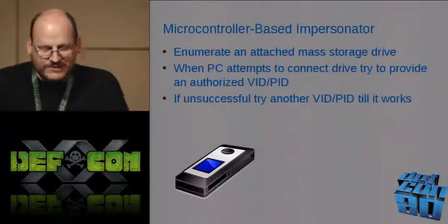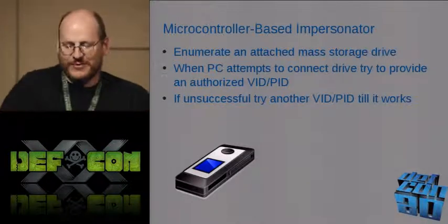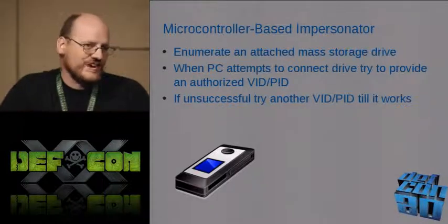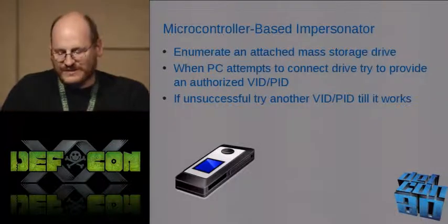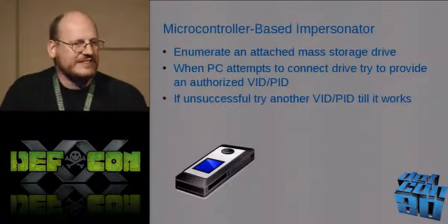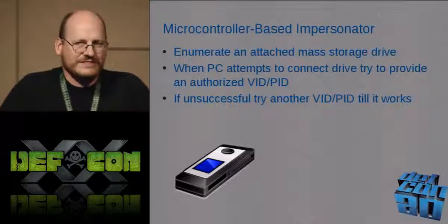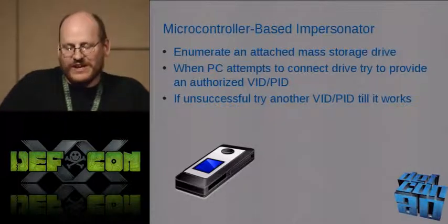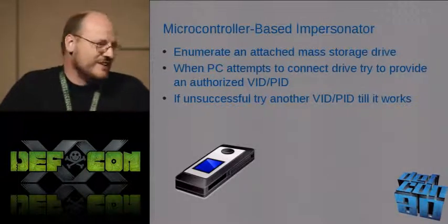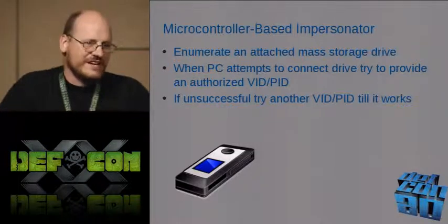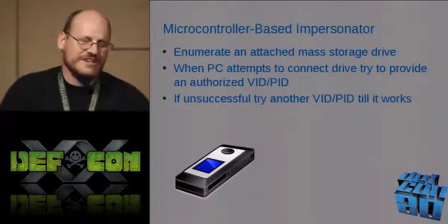All right, so how does this microcontroller-based impersonator work anyway? What it does is it allows you to insert your flash drive, and it enumerates it. And then when you plug this device in the PC, it says, oh, I see there's a new device. Let me enumerate it, and it tries to get an authorized VID-PID combination. If it's not successful, it tries the next one.